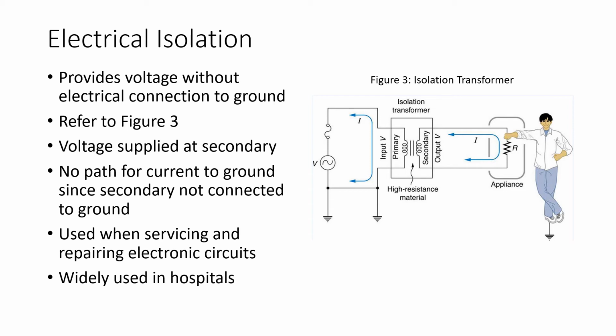And if we plug another piece of electrical equipment, such as an infusion pump, into a grounded receptacle, then there could potentially be a difference in voltage between the chassis of the bed and the chassis of the infusion pump, therefore creating a potential for current to flow through someone that was touching both pieces of equipment at the same time.